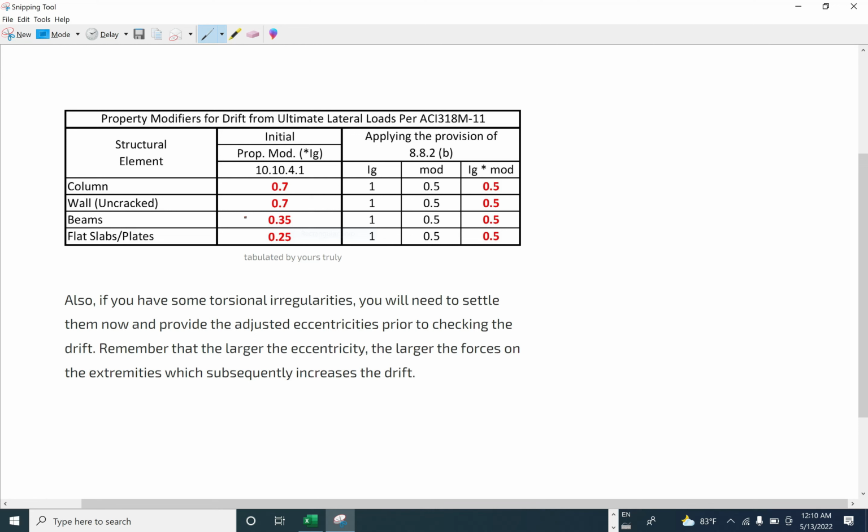After you apply the notional load and the global and local imperfections, you have to modify the concrete thickness, the thickness modifier, to activate long-term analysis and design of the tall building or high-rise building.